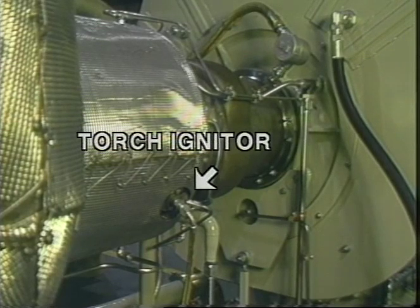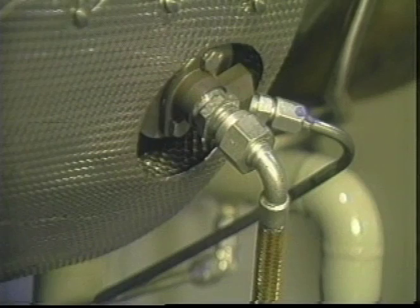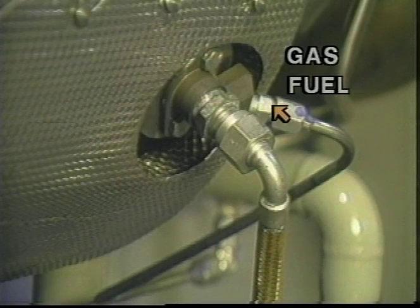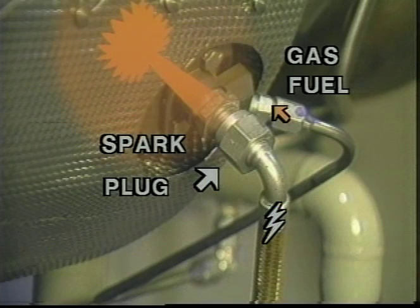The igniter torch assembly is made up of a housing which incorporates a gas fuel line connection port, a filter and orifice, and a spark plug electrode. Ignition takes place when a small amount of gas fuel flows through the igniter plug housing and is ignited by spark from the spark plug. This creates a torch that ignites the fuel-air mixture in the combustion chamber.